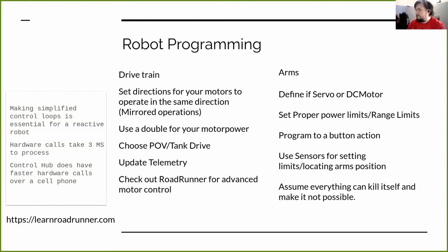Spend the time to invest in learning your system. And that's one of those things: every sensor is going to be a little bit different. So learn how your sensor works. Do some A/B testing with sensors, figure out what's going to be the best case. Because you might have 4 Rev color sensors, and every color sensor should work the same way, but there's tolerances. And so do some testing with your color sensors, see which one is going to give you the better value for what you're trying to do, right?